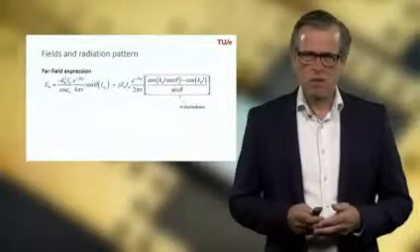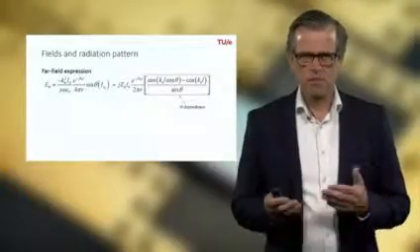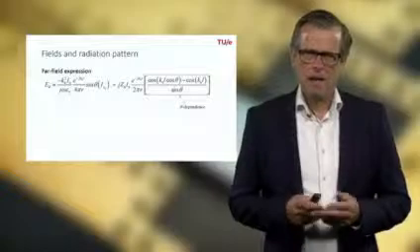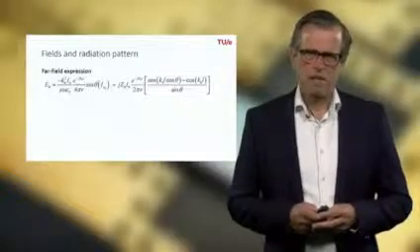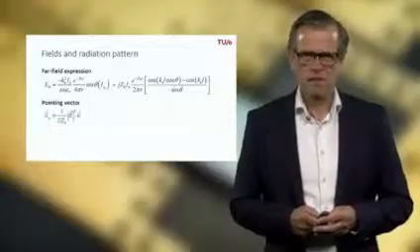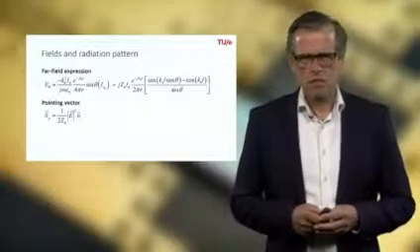Having E theta, we have the electric field. We can calculate, of course, also the magnetic field because there's a TEM relation between the E and H field. And as a next step, we can calculate the power flow, so the Poynting vector, the radiated power. And that was given by this expression as we used before.